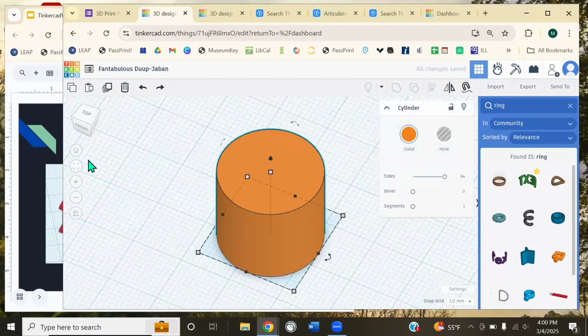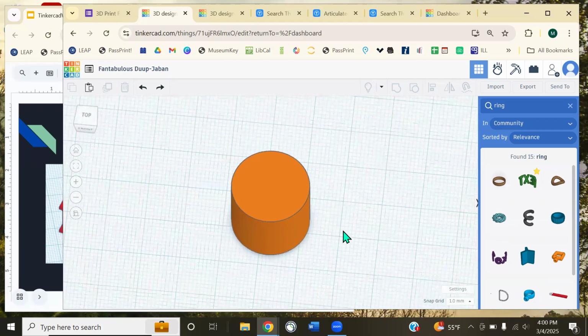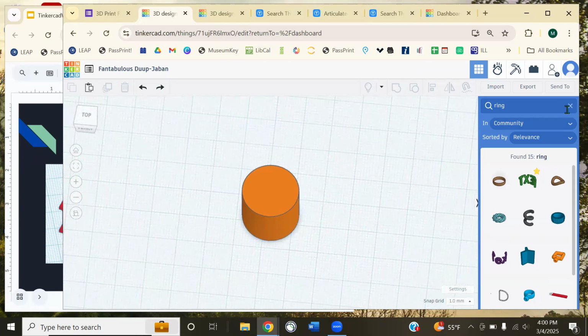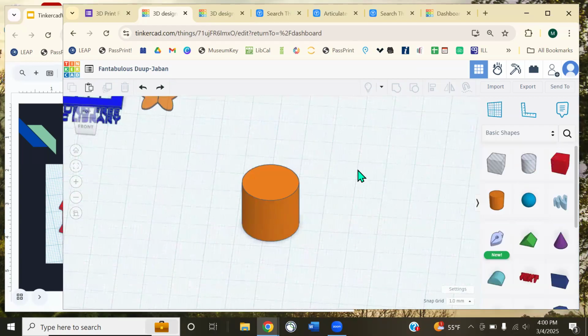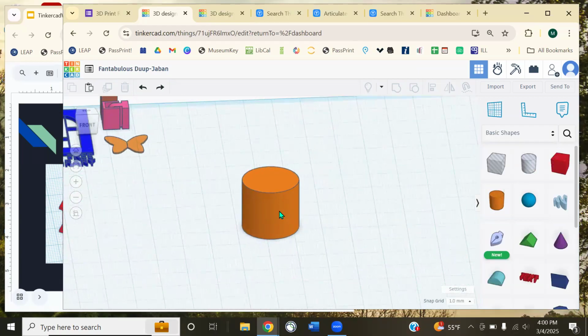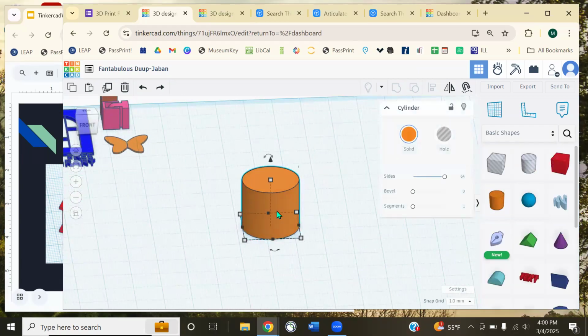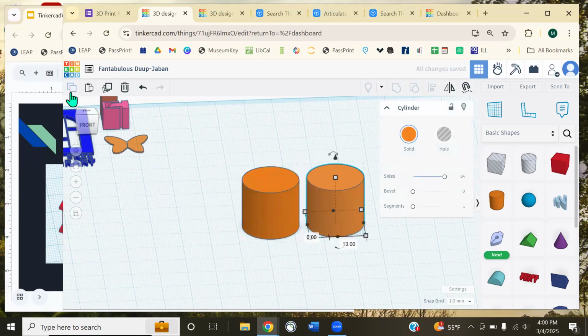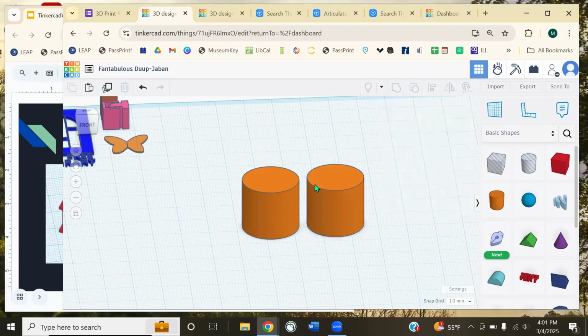What we'll do is modify this to be as hollow as we want. We can change the thickness of the walls, and then we can keep adding on to that with objects that we keep customizing. What I'm going to do is press Control C, Control V to copy paste. You can also use copy paste buttons up this way. Again, all the buttons that we use will be in multiple places. You can do what you want.